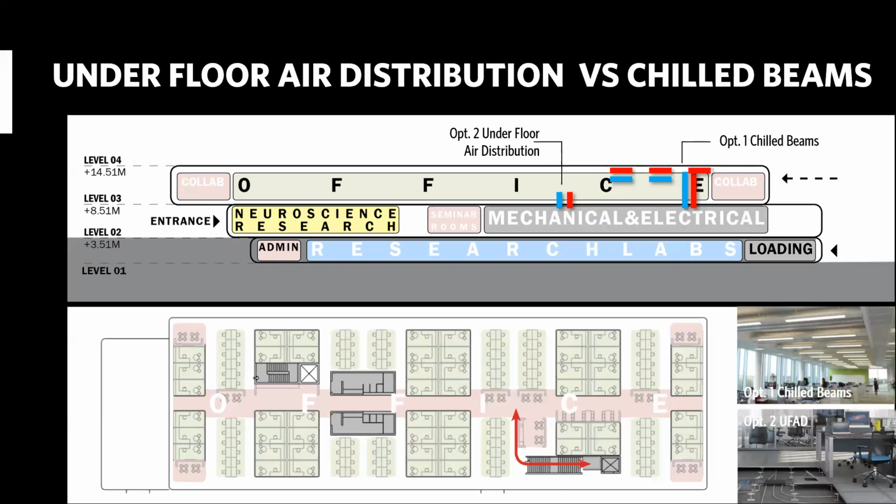And the underfloor air distribution, as many of you know, significantly increases the user comfort. And with the pandemic experience, having the choice to introduce more fresh air to the space, if needed, is a big plus for this alternative. And the underfloor air distribution system is very much compatible with natural ventilation, and our team is now considering automated operable windows to enhance the indoor air quality even more.